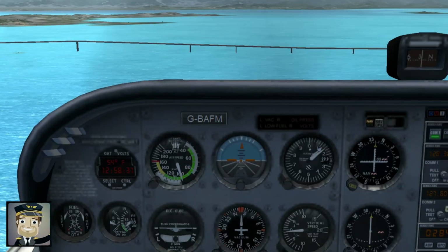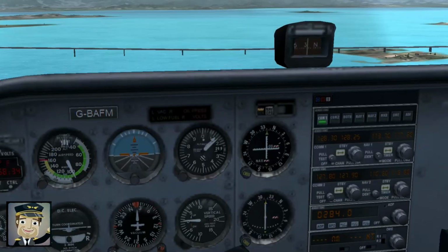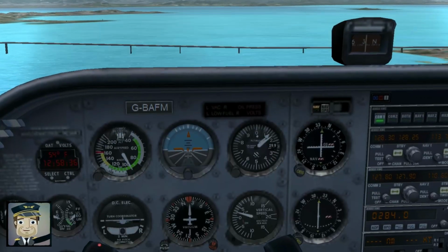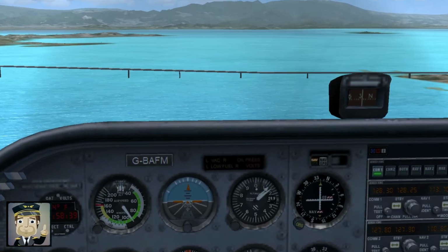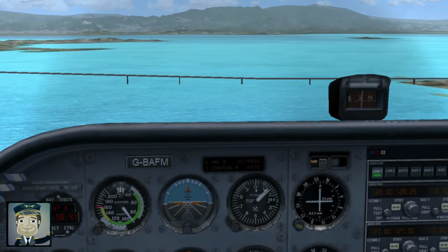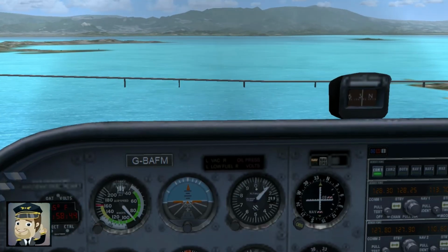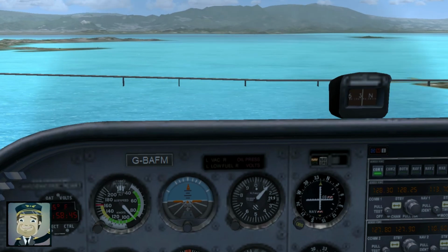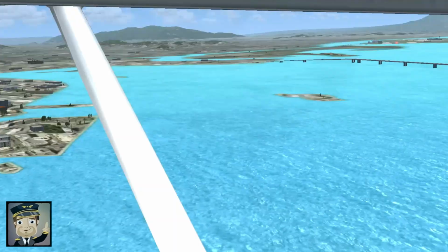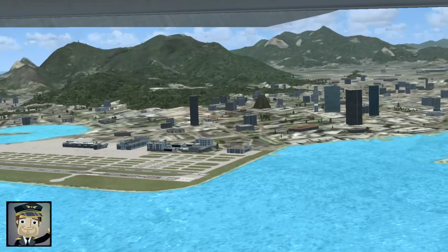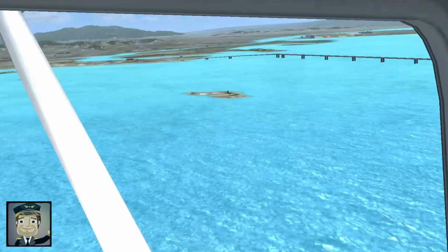When the aircraft reaches a point roughly abeam the runway threshold, the imaginary point where the pilot would descend if flying straight in, it is time to begin the turn onto the base leg. The pilot reduces power further, begins a controlled descent, and turns left to fly perpendicular to the runway once again. The base leg brings the aircraft from the parallel downwind path toward the alignment needed for final approach. Depending on winds, more flap may be added, and the pilot adjusts pitch and power carefully to maintain the desired descent rate and approach speed.